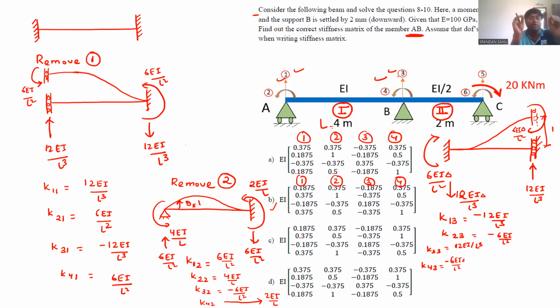So anyhow, both are getting hampered due to that displacement of coordinate 3. So the combined effect from both spans will come because we are doing it like a superposition. We are not considering the second one for the first one. We keep the first one ideal and do it for the second one. So when you combine it, you will get the overall response of the structure. Correct?